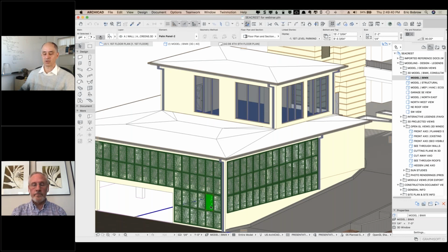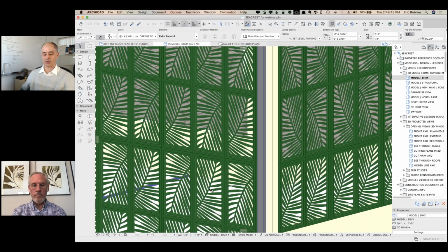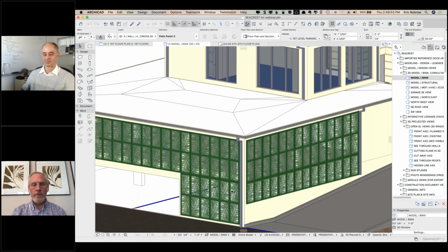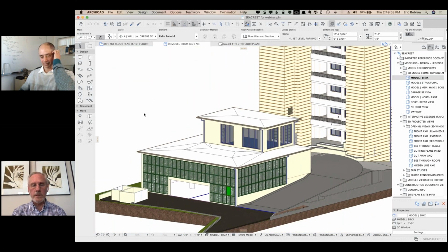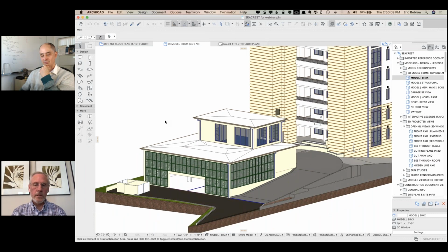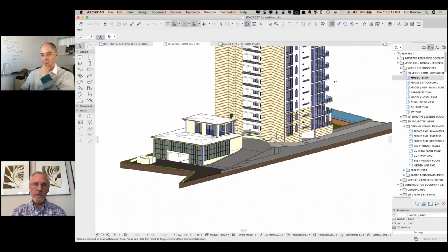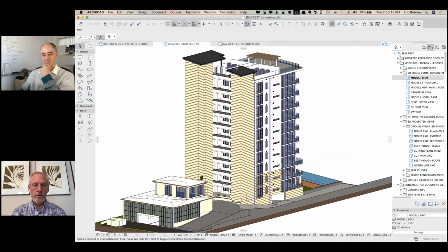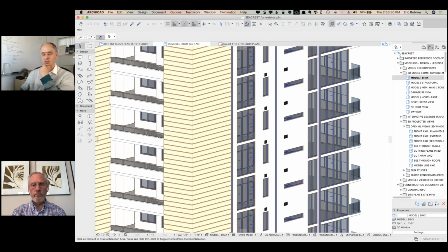And so this little screen we had talked about. So you modeled this on the plan, turned it into Morph and flipped it up? Yeah, and the screens with the idea we had, because there's two developments, one on each side of this, and this ancillary building is kind of in the same location as the clinic was, and it was just a single-story building with a hip roof on it. So we're trying to keep the look of it and the profile down as much as we could, and we thought we could disguise it a little bit with these palm frond kind of screens that we put in and still keep the parkade open to the air, so we can avoid having to put mechanical ventilation in that part of the parkade.